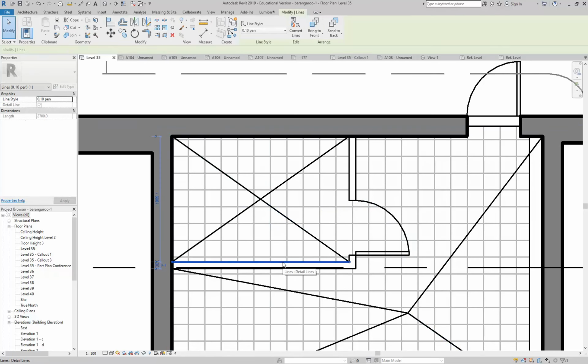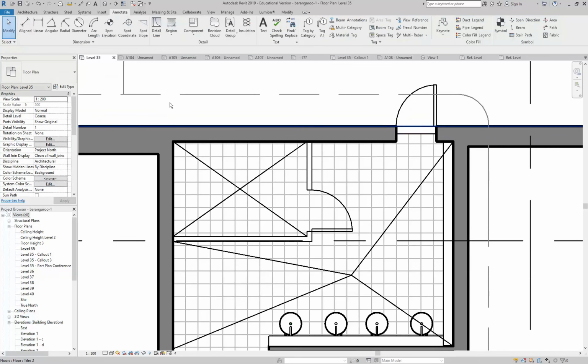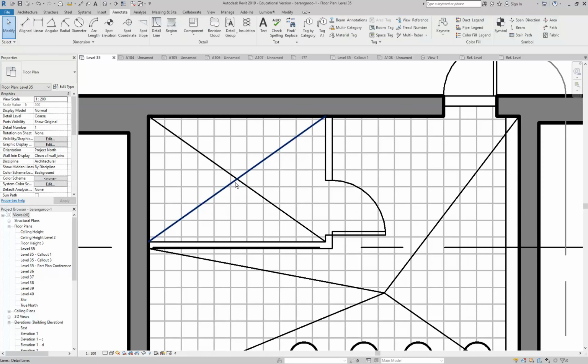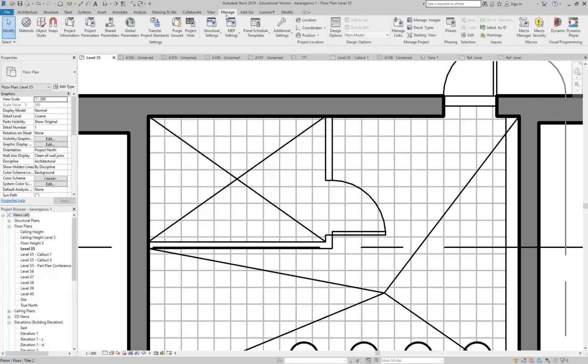Okay, because the thing that's never obvious with AutoCAD is that there is no golden rule for your line weights. And people think, oh, why can't you just give us the line weight that we should be using? And there isn't, because it changes depending on whether it's cut or in projection, of course, but then also depending on the scale. Yeah, that's right. Now you know. But you've got to do it to understand it.